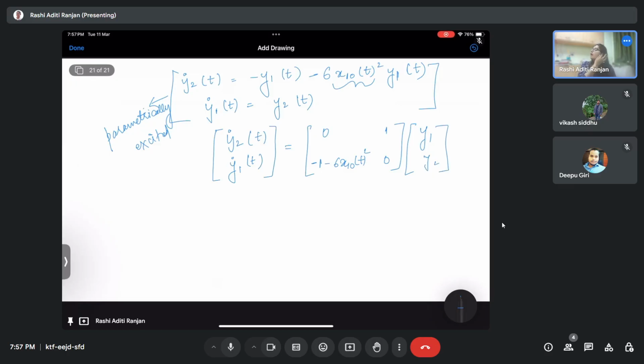Now what I can do? I can use the ODE45 and take two different initial conditions, and then I can use those initial conditions to get the monodromy matrix, and then on the basis of the monodromy matrix, I can find out the eigenvalues. On the basis of eigenvalues, then I can say whether my periodic solution is stable or not stable. How? Because if the eigenvalues are coming out to be positive, it means that wherever I'm starting, my system is going to diverge from that value. It is going to go away from that value, which means that my system is actually leaving the periodic orbit, which I considered as the equilibrium point. So my periodic orbit is unstable. If it turns out to be negative, then I'll say that my periodic orbit is stable. Okay, that is how we are going to use the concept.